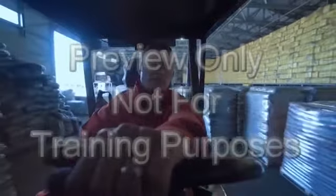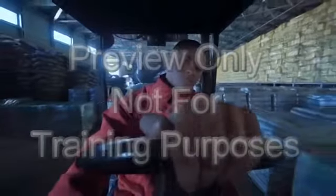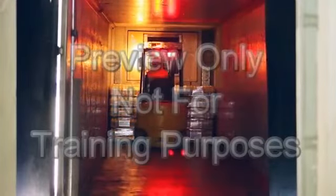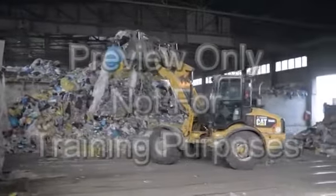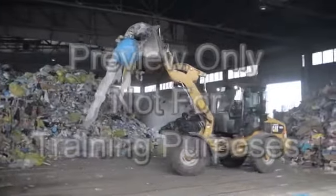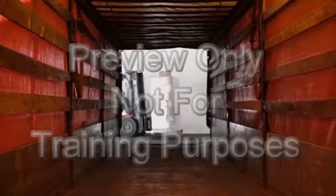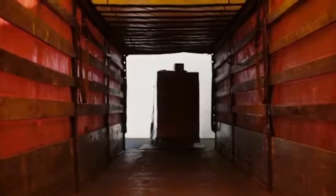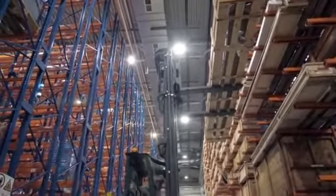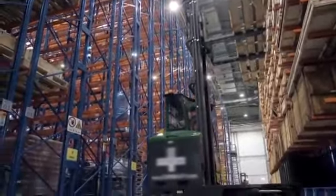Operations. While driving a forklift, operators must be aware of potential hazards, such as mechanical breakdown, fire, overheating, and leakage. Forklift operators must always follow safe operating rules. Never overload a fork truck or extend a load past the center of gravity. Always maintain control of the forklift. Keep a proper lookout and operate the forklift at speeds appropriate for the operation and worksite conditions. Never allow a person to stand under or pass under the elevated portion of any truck, whether loaded or empty.